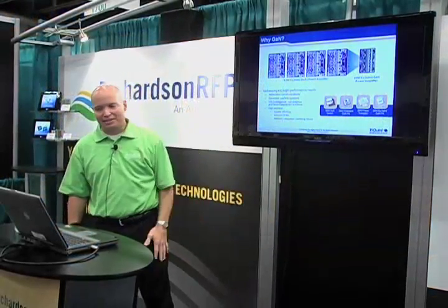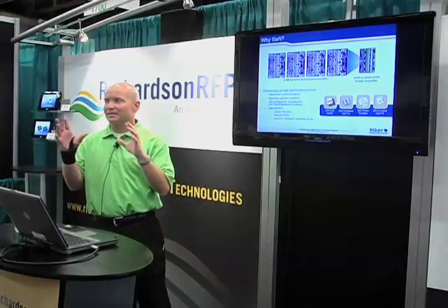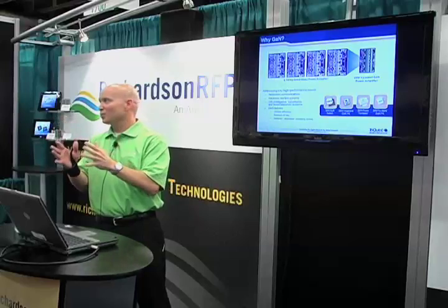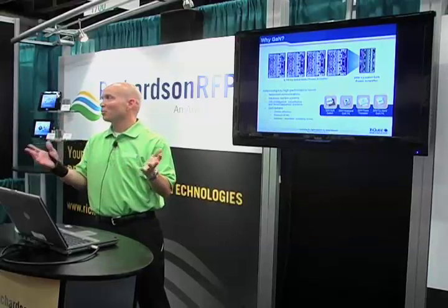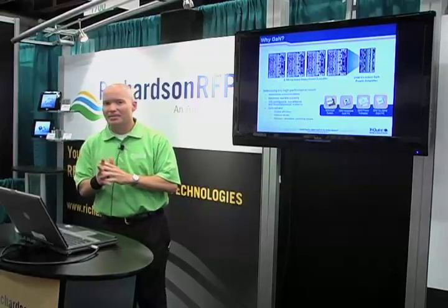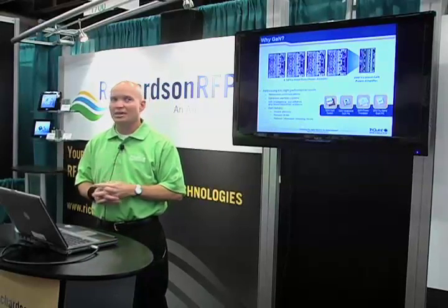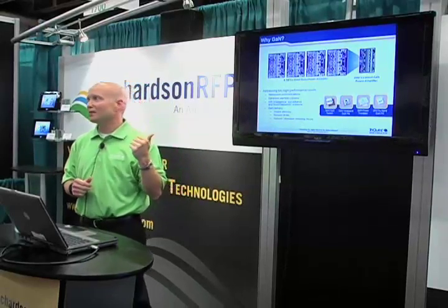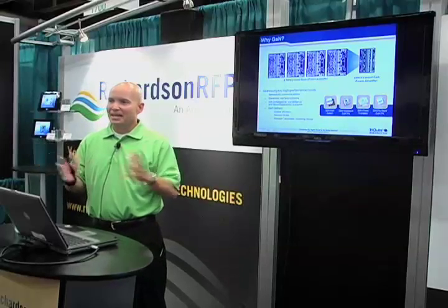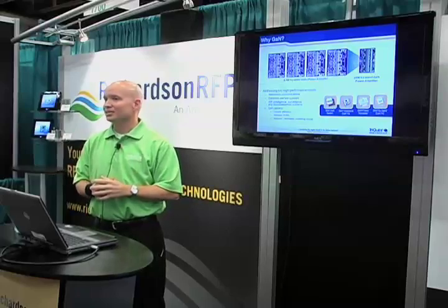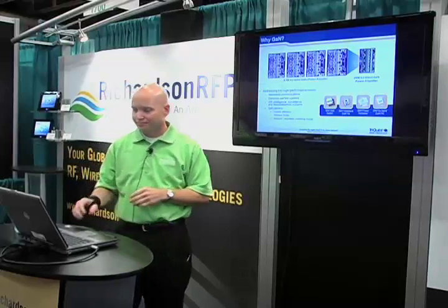Anyway, that's a pretty good pictorial from a system standpoint. If you can use only one chip versus combining four or more in some cases. We have some customers that are combining 16 to even up to 32 gallium arsenide chips. Some of the GaN chips that we're developing can support that same application with one or two chips.